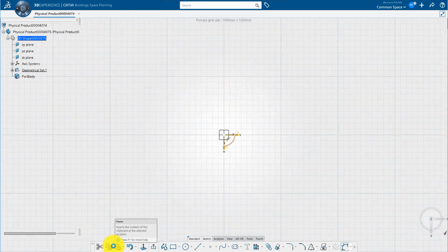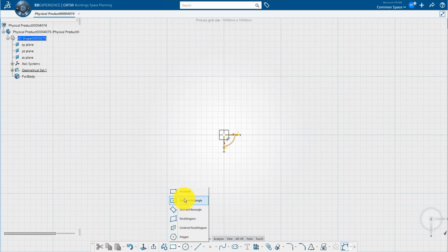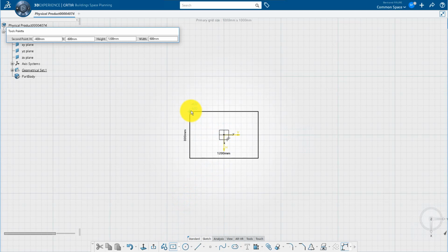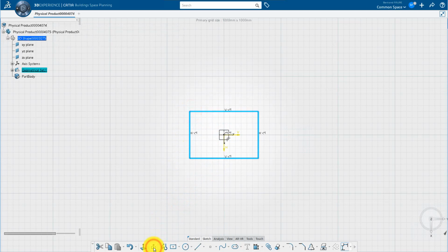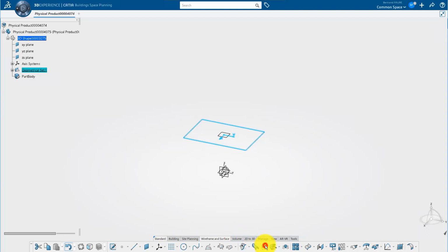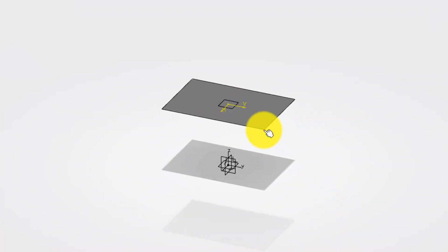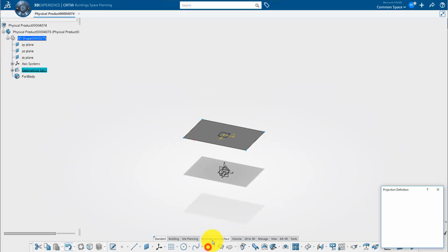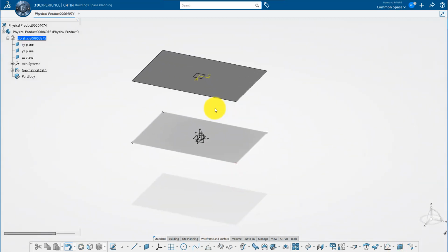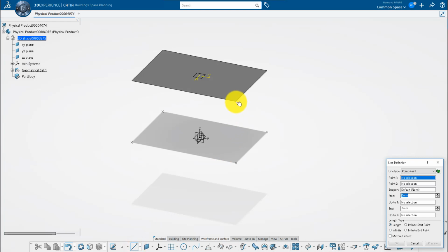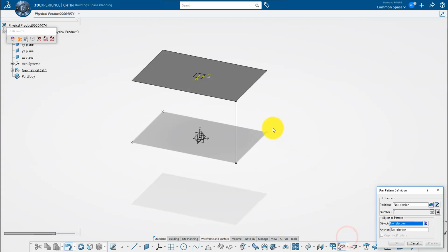Create a sketch on it. And draw a centered rectangle. Fill this contour to create a tabletop. Press Ctrl key for multiple selection, then select carefully the points on every corner and project them on the XY plane. Draw a line from one corner to the ground and replicate this line on other corners with the user pattern.